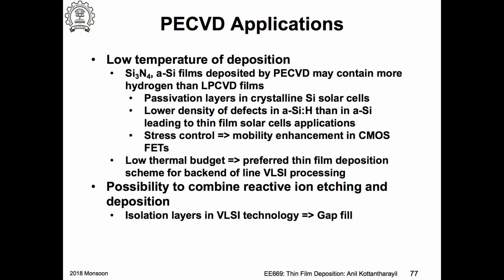Okay, this is not necessarily bad, because, for example, you might have heard about thin film transistors used in displays. Displays use thin film transistors, and you don't use crystalline silicon for making them. This is huge, right? Displays are very big. So you can't have that big a crystal wafer. So how do you make this? You have a glass, and something is deposited on it. So this is a thin film, and you use that as channel material in your transistor.